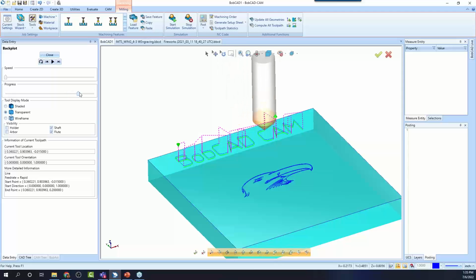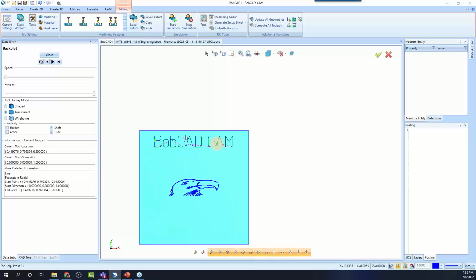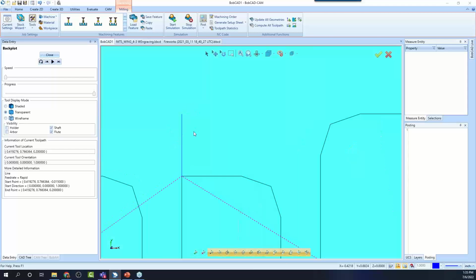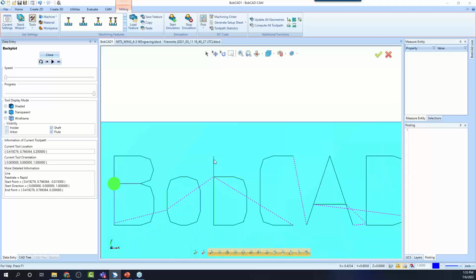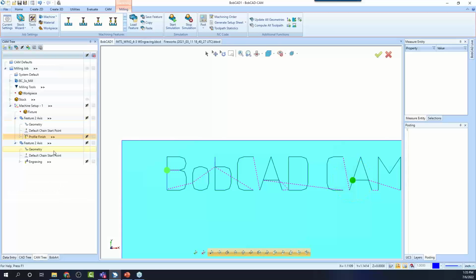And actually, if you look at this example here, we go to a top view. Top of the letter B here, it did not cut this section. It got all the way around this section, but it stopped there. So again, an indication that really you should have been using an engraving operation, which you can see picks up that area versus a profile operation.